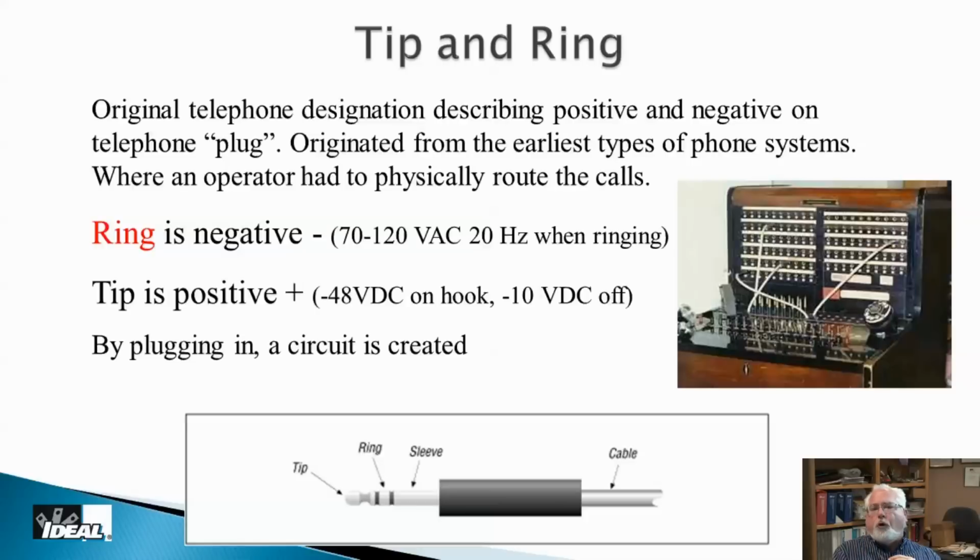A lot of us know that normal AC is 60 hertz. And you understand, old phones have mechanical bells in them, clanger bells basically. And if they put a 120 volt or 90 volt signal down a cable at 60 hertz, that bell would try to clang at 120 times a second. And so your ear would actually hear a solid tone.